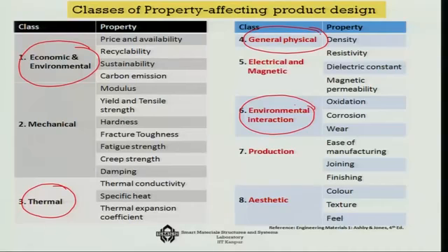So, you need to give even protections from corrosions for them. Oxidations and corrosions are very important factors in terms of those mechanical systems which are generally subjected to the possibilities of environmental vagaries or the possibilities of harmful chemicals, say for example gas pipelines. Okay. So, there the chances of corrosion are very high. So, you need to choose a material which will not get corroded so fast, in that way reducing the life of the pipeline.